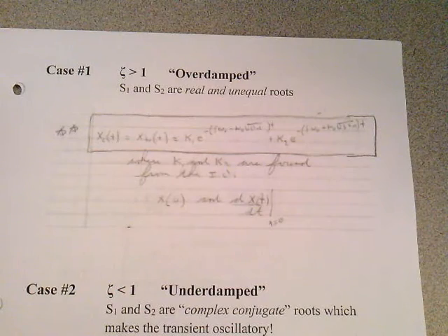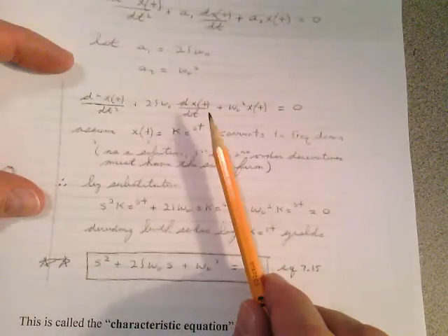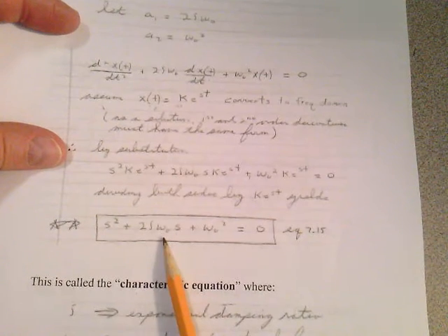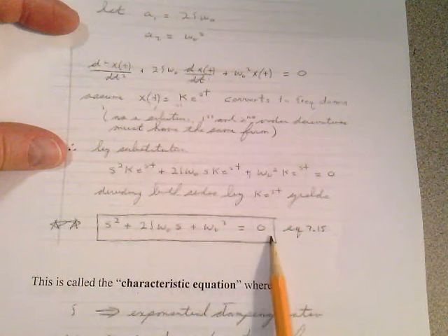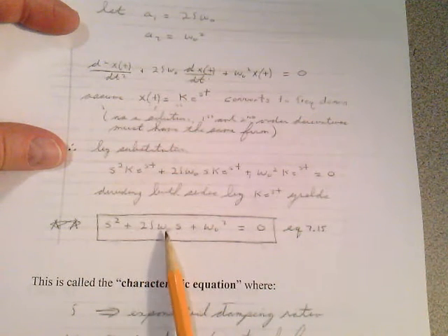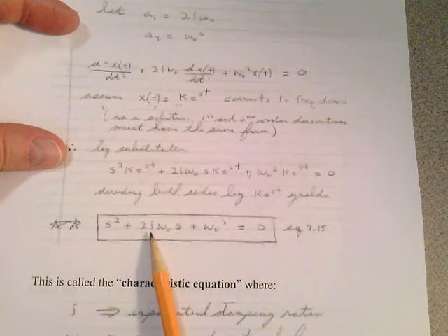If you remember the last lecture, we developed the response equations for second order systems that had R, L, and C elements in them. And we said that the analysis of the differential equation would lead to a characteristic equation. This is on page 92. In this characteristic equation, we took the coefficient of the S term and set it equal to 2 zeta omega 0.